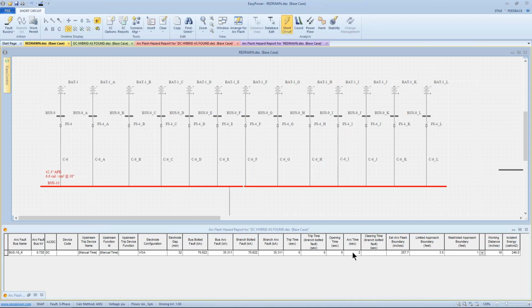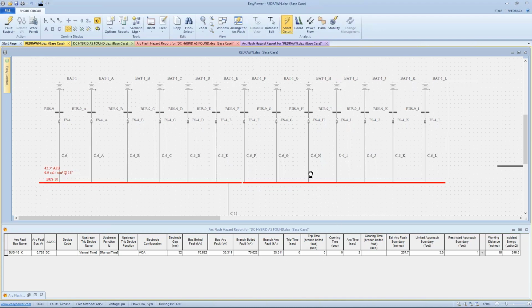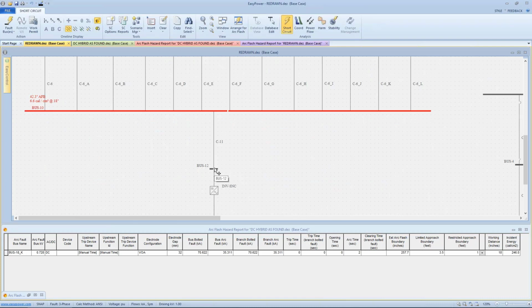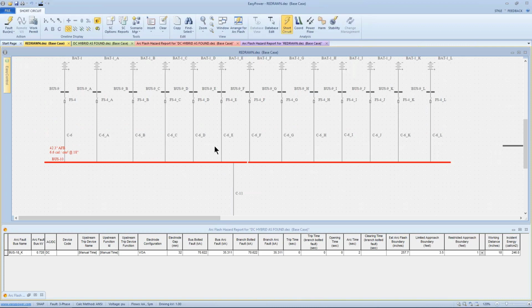Now again, this is still limiting it because we're talking about the DC current, but the principle is each of these fuses will protect the main bus from a fault current being contributed from that individual battery.